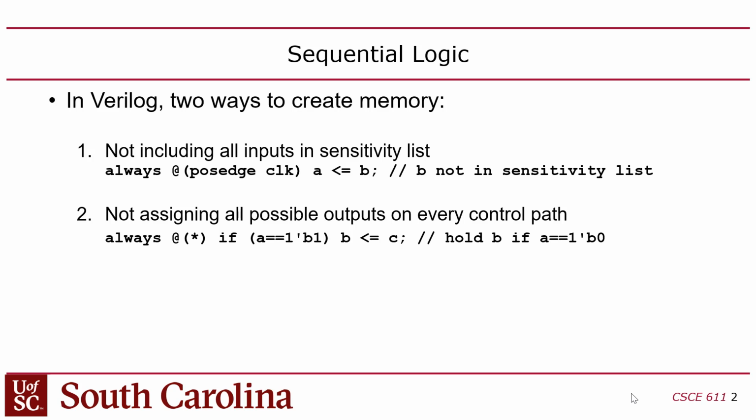So last week I was talking about sequential logic, and the reason I was talking about that, of course, is the CPU is a collection of sequential logic and combinational logic. So we're going to have an instruction memory in there that's going to be a ROM, single-ported ROM, and the size is 4096 by 32. So it'll have the capacity to store 4096 instructions, and it'll have an address which will be fed by the program counter, and that will be a word address.